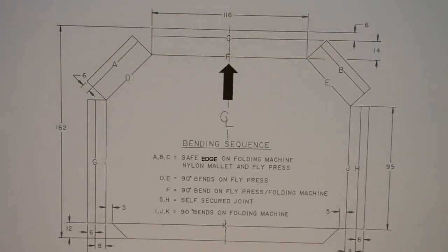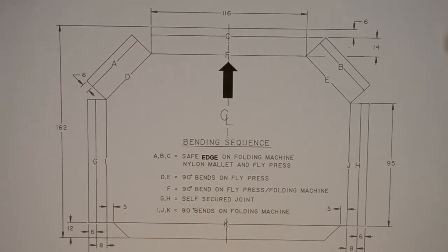It'd be nice to think that datums were all that simple. So here we've swapped over subjects. Now we're looking at sheet metal. Those of you who've done this will recognise this as being one of the ends of the sheet metal toolbox, and it's a busy drawing. There's lots of dimensions going on here, and so when you're faced with producing this, the first thing you have to ask yourself is, where is my datum point?